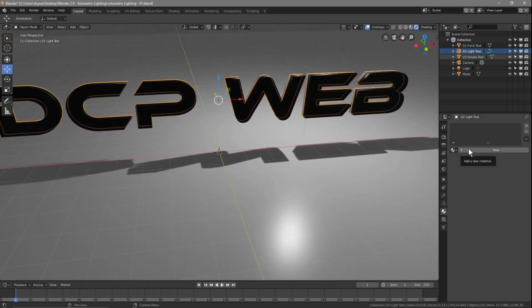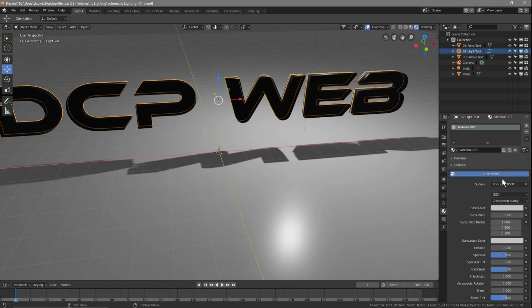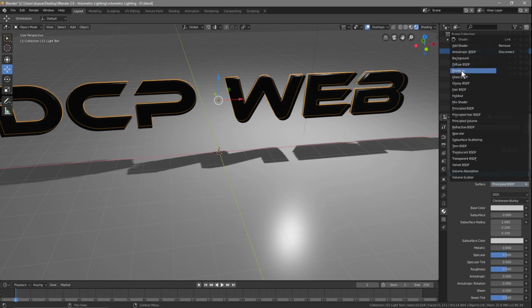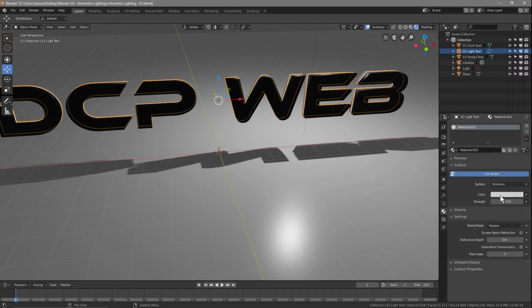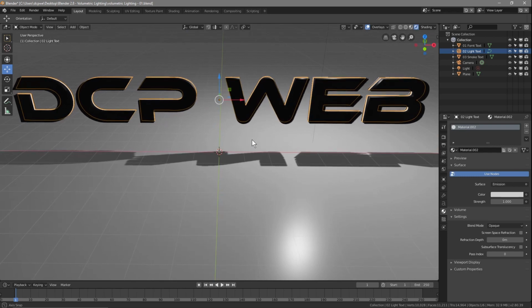We'll create a new material for that one, so click material here, make sure the light text is selected, we'll click new, and this one we'll set to emission, and we'll leave it as white for now. We can change that later. Okay,